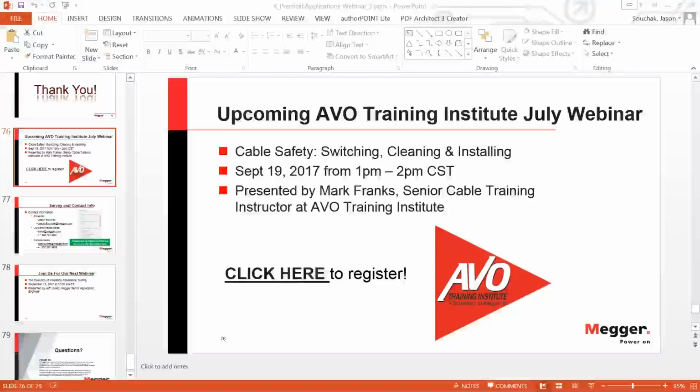That's really the strength of PD measurement, with any type of layered dielectric materials you have, like you have in terminations and splices. PD is absolutely the best tool to show not only that you have a problem, but also how bad a problem you have. It's a very quantitative and qualitative measurement, and you get a location. So that's a home run.